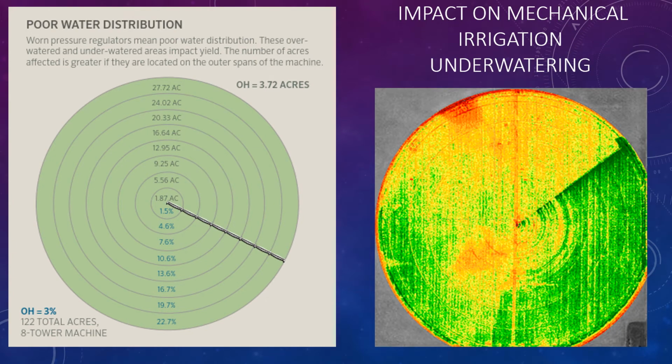And let's take a look here now at underwatering. And you can see there are vast areas that aren't getting enough water all the way along. You can see the wheel tracks where their sprinkler package isn't quite good enough. And of course you can see this pivot's probably moving this direction. And this is the watered area, and you can already see dry spots. But these are particularly egregious because all the way here it's underwatered.